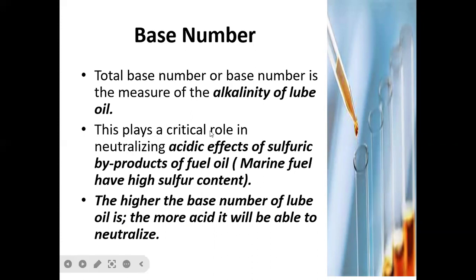This plays a critical role in neutralizing acidic effects of sulfuric byproducts of fuel oil. Marine fuel has high sulfur content. We've discussed this already in our fuel video, but it is now limited to 0.5% according to MARPOL in the year 2020, after the pandemic.